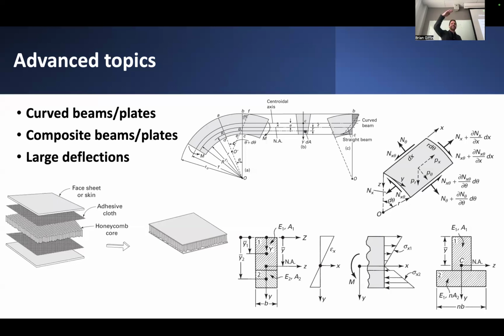And that has to do with the fact that right as you transition from that concrete deck and you go down into the steel girders, there's basically a discontinuity in the representation of what the resulting bending stress distribution would look like. So it'll look kind of linear through the depth of the concrete deck until you get to the steel, and then all of a sudden it'll jump to something else. That's true also if you have, let's say, steel reinforcement inside of concrete. The apparent stress carried by the steel reinforcement is going to be different from the surrounding concrete.